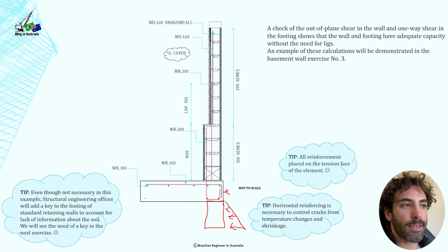And what I'm saying here is that at least all the engineering offices that I know will install a key even for this type of wall, even though it might not be necessary. There are a lot of factors that we don't account for, and soil is always really hard to quantify the parameters. That's why we are going to use a key for a real life project.